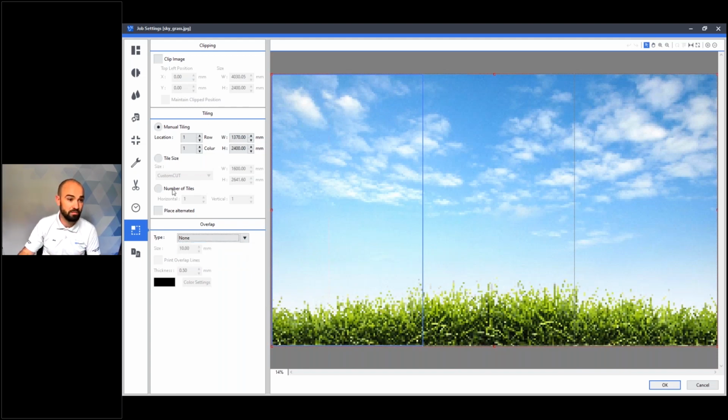So if we did have, just say, for example, a horizontal split as well, then it would add an overlap in the horizontal side as well. What I'm just going to do is put this back to 3 tiles, and we're going to say I want top left, and then we can specify the size of the overlap. So in my example, I use 20 millimeters, but you can use whatever. It normally is down to the fitter as to what their preference is for the overlap type.